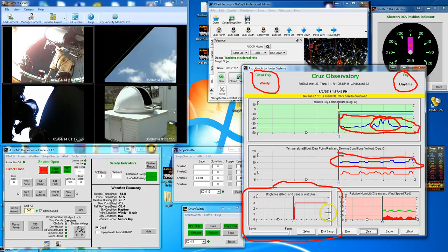line, or actually graph, that would appear. If it's raining, the sensor would detect that and display it here. The Astro Alert version 3 is extremely sensitive to rain. We borrowed the technology from the folks that make the high-end auto windshield wiper controls for vehicles. It detects extremely small water droplets on a little transparent dome that it's built on, and immediately will let us know whether it is raining or heavy dewing conditions. The program at that point has a capability to take that as a bad sign and immediately close the dome.